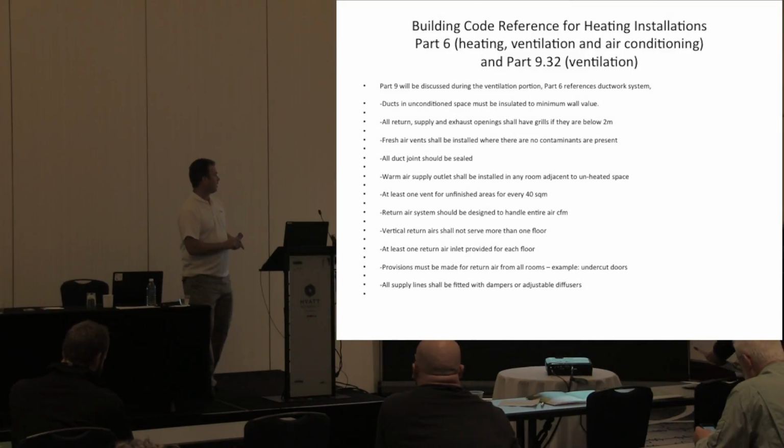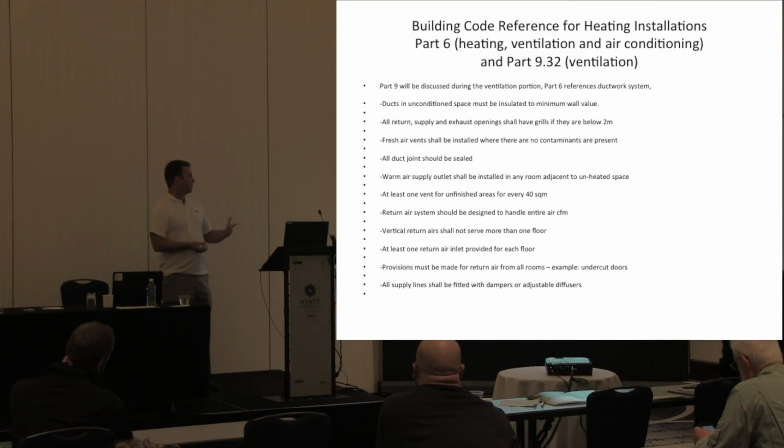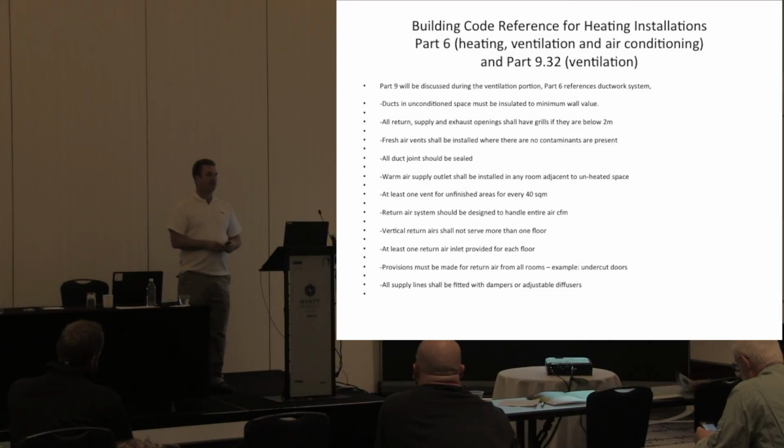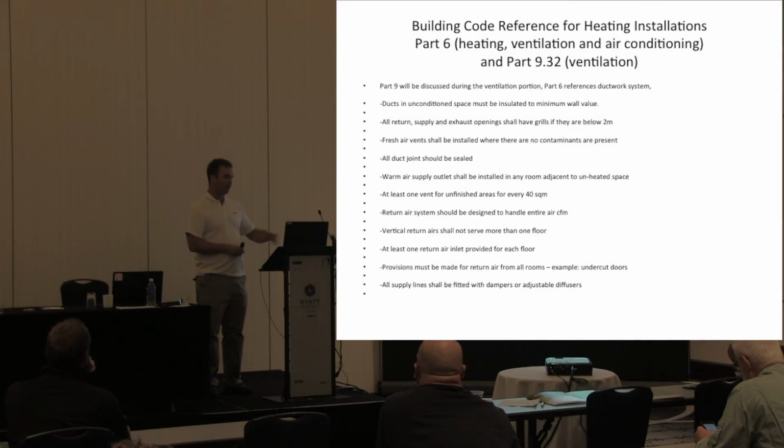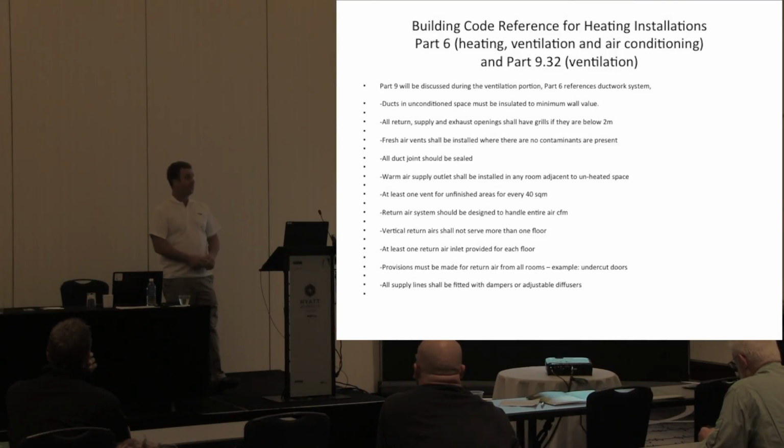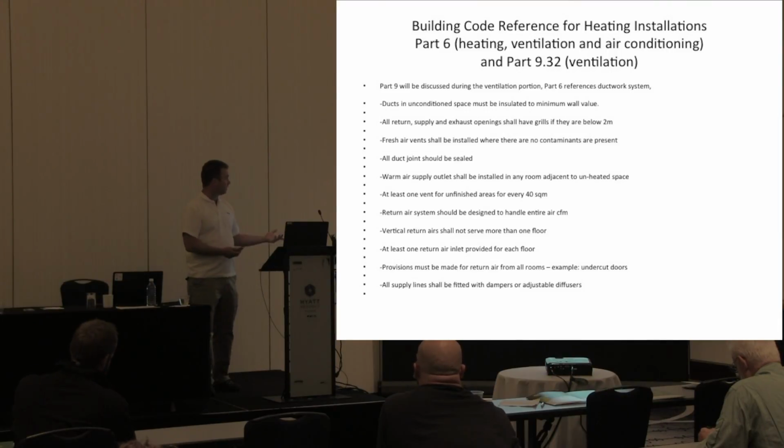Fresh air vents are to be installed where there's no contaminants. So don't sit it where you park your diesel truck every morning, because especially if you know that's where it's going to be, all you're going to do is pump all that stuff into your house. Have some thought process, and hopefully the installing contractor doesn't put it beside the one parking spot in the whole house. So try to put it somewhere where it's actually going to get fresh air, because all houses have fresh air now, which is what Terry went over already. So not like before. All duct joints have to be sealed now.